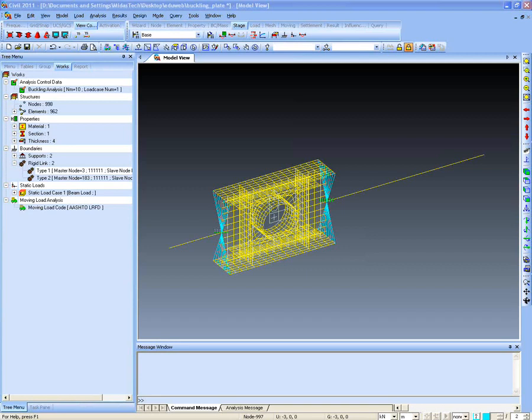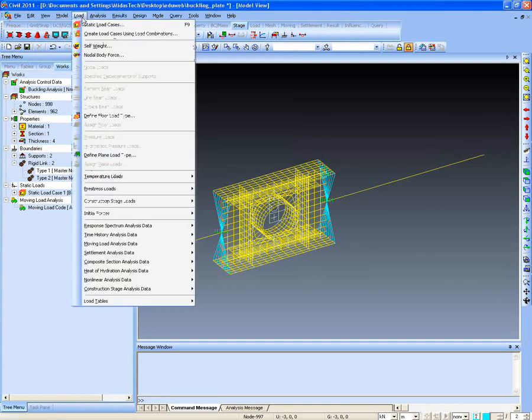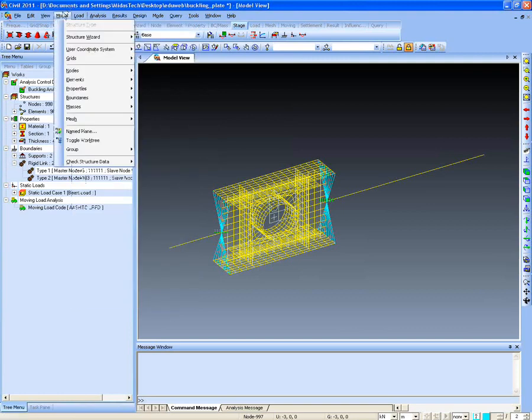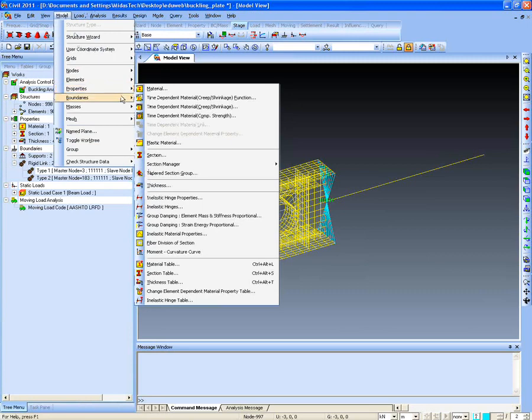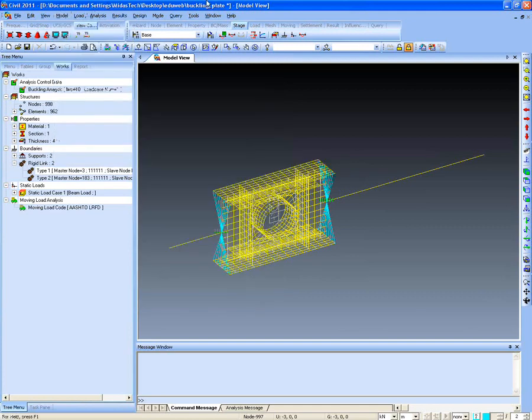Mr. Robert asked, how do we model lower E cross I on the inner supports of continuous composite girders? Yes sir, we can do that by applying the section stiffness scale factor. After applying the section stiffness scale factor, you can reduce the stiffness of the section, and if I'm correct, if you are talking about the cracked section, you can also simulate that characteristic. You can define the cracked section for the composite sections, and then in MIDAS Civil it can be analyzed as a cracked section.